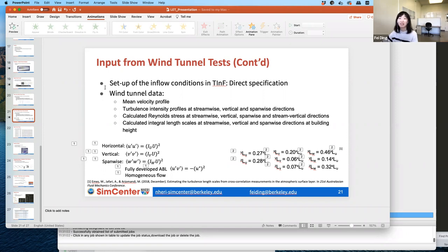But if you do have a very large magnitude of wind velocities when you're simulating the buildings and you want to save some computational cost, probably you can also impose some velocity scales, similar to the wind tunnel, to model the CFD simulations and save some computational cost.